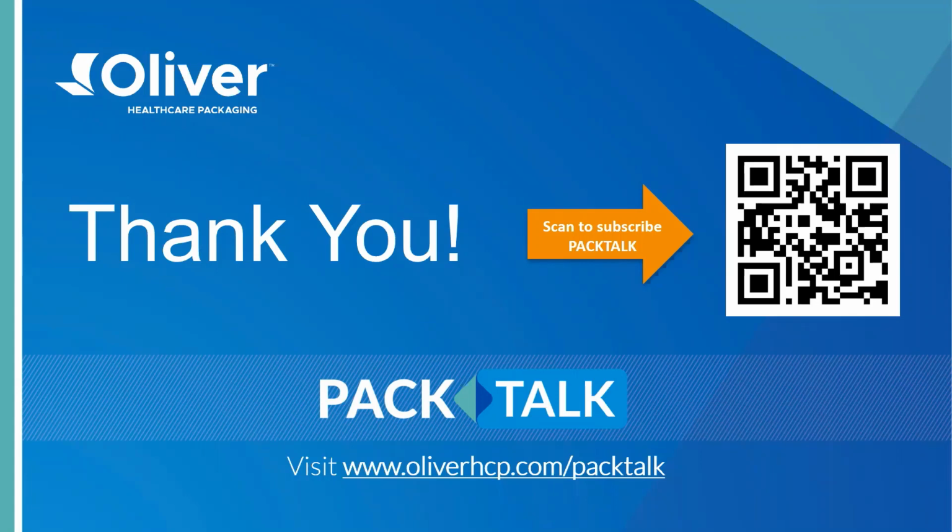I don't have the DuPont literature in front of me, but let's just say generically that Tyvek is around 22 seconds Gurley porosity. Adding the coating might close off the sheet to the point where instead of 22 seconds, it's 45 or 50 seconds.